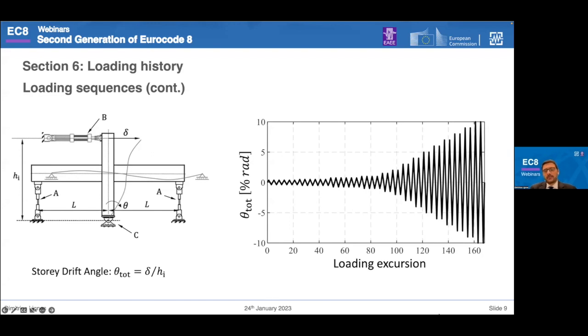But because of course loading history effects are important, the technical specification does not preclude the use of other load histories that reflect demands, for instance, at large deformations, if we are concerned, for instance, with incipient collapse and quantifying performance for incipient collapse.